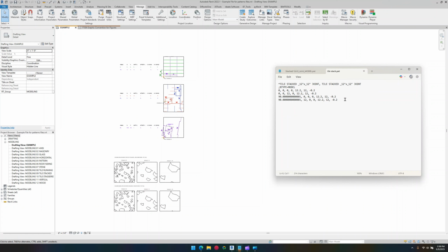If we export it, none of the commented information made it out of Revit. What's even weirder is the actual units didn't make it out either. So I'm assuming when you import it back in, which works, it's just going to assume whatever the system unit is that it is currently in if it doesn't have it specified.